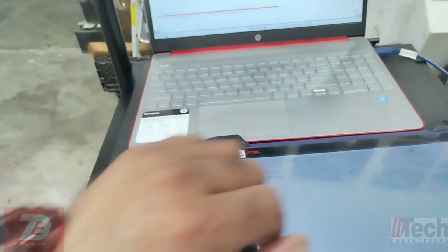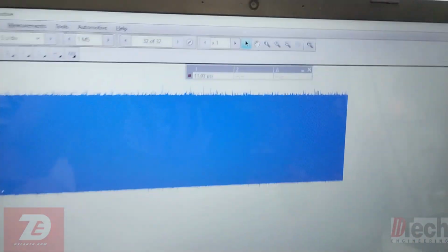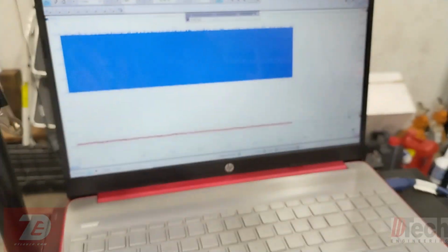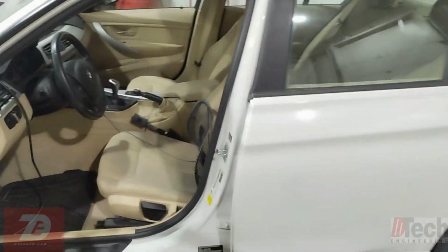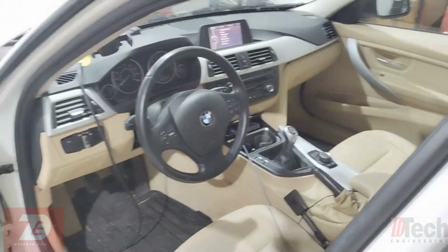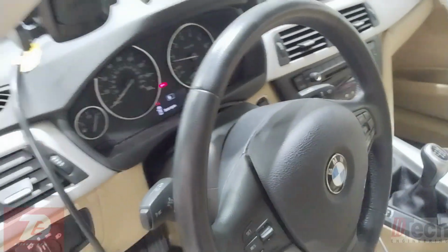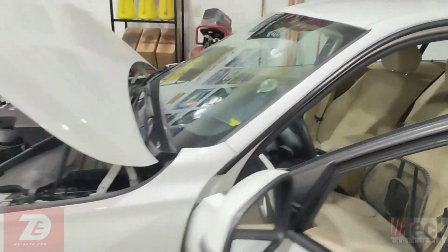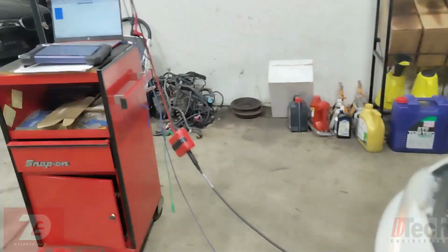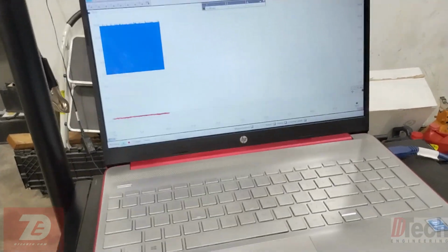Okay, so not too much longer after that, we actually ended up dropping about 10 psi. So it's definitely dropping and holding, even though it looks like it's getting lower than what it needs to be. Still no error message. But we know we are lower than what we had started.